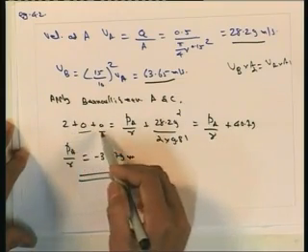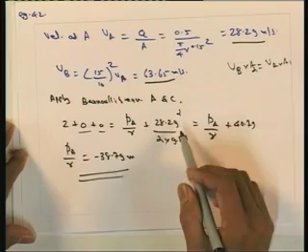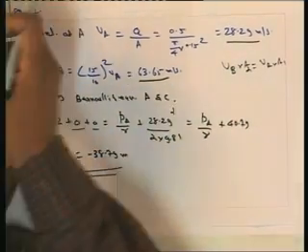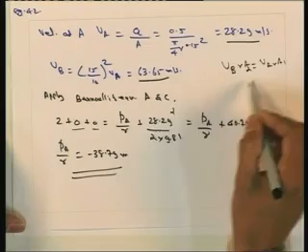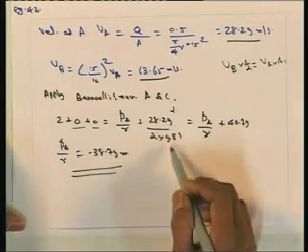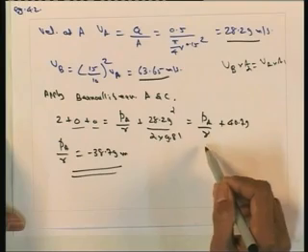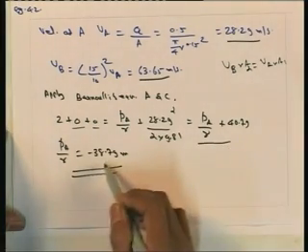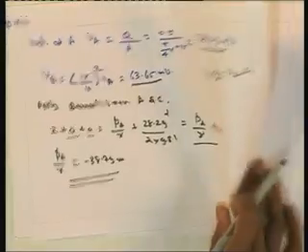So 2 plus 0 plus 0 is equal to P A by gamma plus V A square by 2g, that is 28.29 square by 2 into 9.81. That gives P A by gamma finally as minus 38.79. So here we have seen a few applications of how we can solve various problems using Bernoulli's equation.